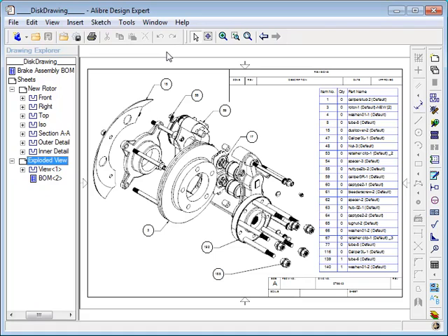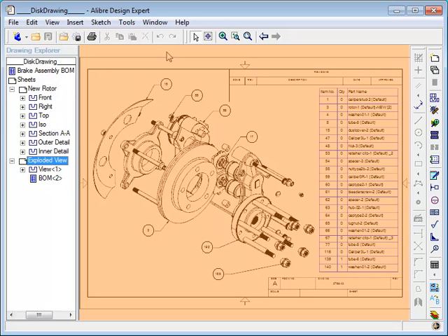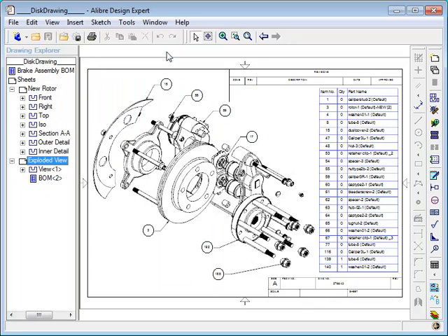Notice how the layout is similar to part and assembly workspaces. For drawings, the work area displays individual sheets and the views they contain, instead of a 3D model. The tools for adding sheets and projecting 2D views are on the Detailing toolbar, located on the right edge of the workspace. The sheets and views you create are recorded in the Drawing Workspace's Explorer window, called the Drawing Explorer. It shows an outline of the drawing's contents.